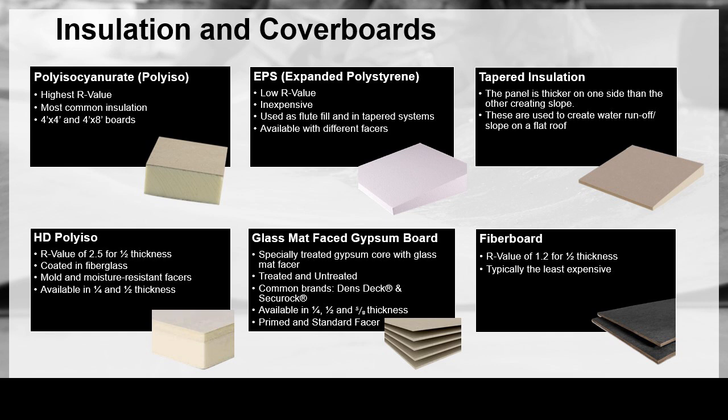And when I was learning about insulating the top of a building, I was pretty confused because, being a homeowner, you see insulation in your attic, you don't see it on top under the shingles. And the reason for that, according to local building code, is that if you have insulation on the exterior of a building, you actually halve the amount that is required. Insulation is very expensive, so local code for me is R30, which would be 2 layers of 2.6-inch thick boards of polyiso. But if you were to put the insulation inside the building, doubling that would be R60.